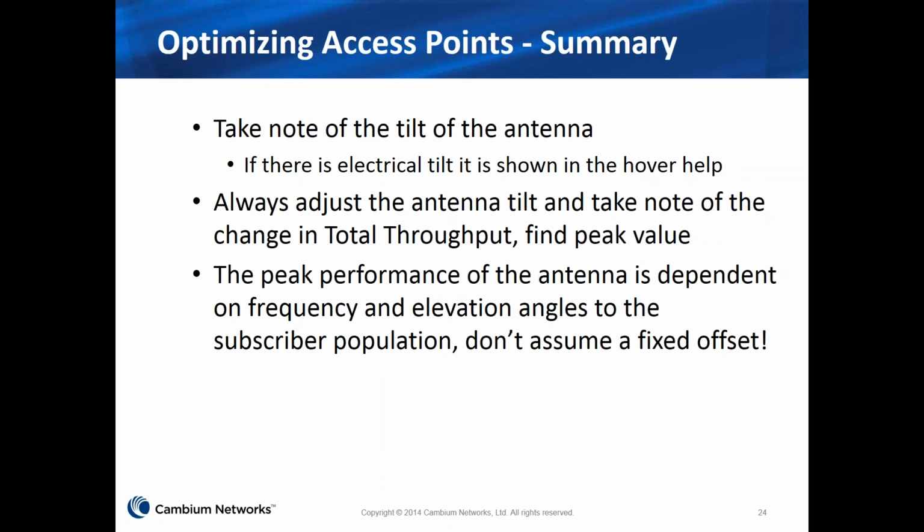Where we're also seeing a need to go through this process is if you have sectors which are already planned and deployed with PMP 450 with original antennas, and you want to look at the improvement in performance you may get by switching to PMP 450M with its antenna with the down tilt. Then you need to do more than just change the product from PMP 450 to PMP 450M. You need to also adjust the tilt, otherwise you won't be seeing the best that the 450M can give you.